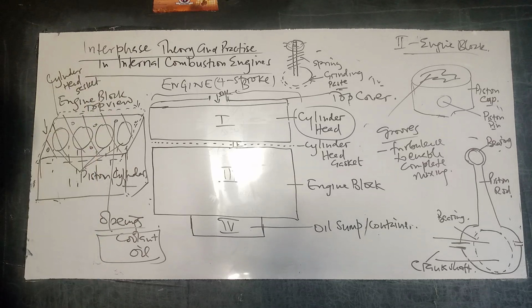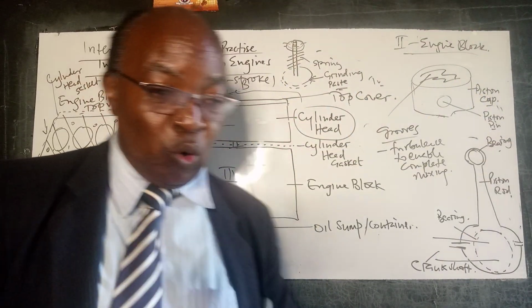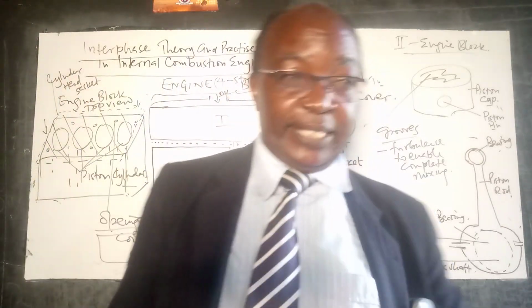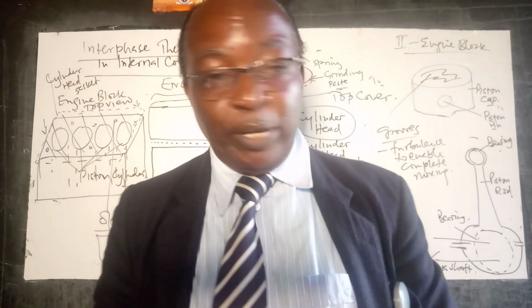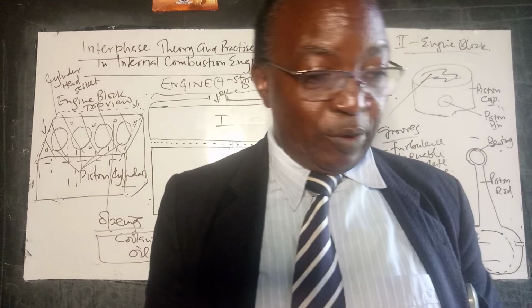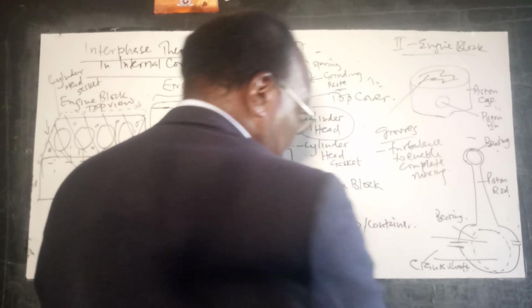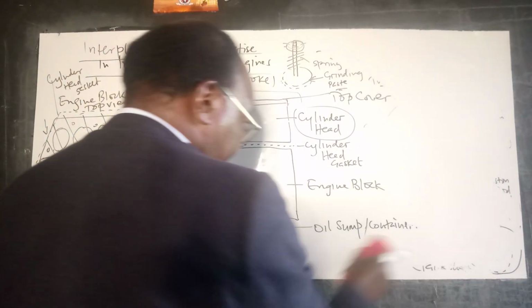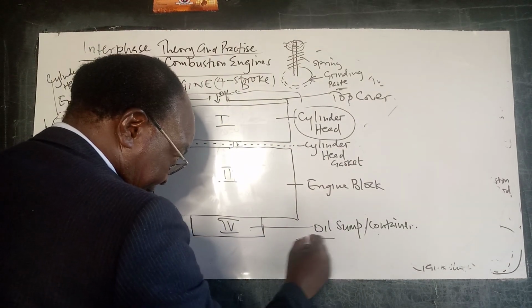Now, if, for example, your cylinder head gasket gets overheated and is destroyed, then one of the things you will see, if you look at your cooling system, is taints of oil in it. If your cooling fluid is liquid water, for example, you're going to see a mixture if you look at the radiator, which is also one of the cooling systems. Let us say we have a radiator here, connected.